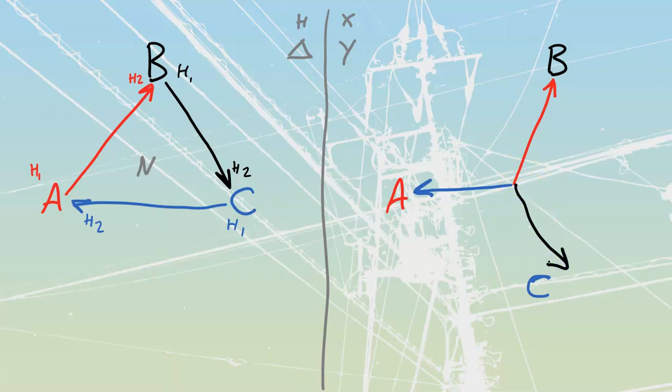Okay, arrowheads, are those 2s or 1s? 2s. Excellent. Thank you, class. Those are all going to be 2s, so I'm going to label them all as my X2s. X2, X2, X2 over here. And if I've got all the X2s labeled, that means the opposite end has to be my X1s. X1s, like that. So we've got line A, line B, and line C that are all labeled up here and ready to go. I'm just going to move this guy just a hair over there so it lines up. Perfect. This is my voltage diagram.